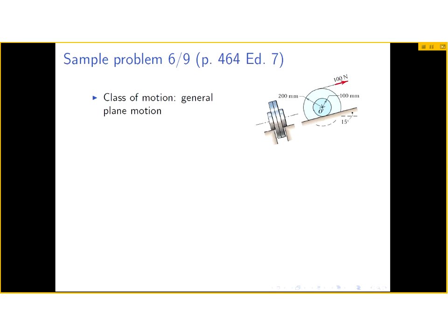So this brings us back to the question: how should I know that I should use an energy method to solve a problem? This is the answer. When you have a problem where clearly you need to solve the problem over a time span, from a certain point to another point in time, and you do not have something like the omega d omega is equal to alpha d theta type of equations, then you should really consider whether this is perhaps a problem that I can solve with energy methods.